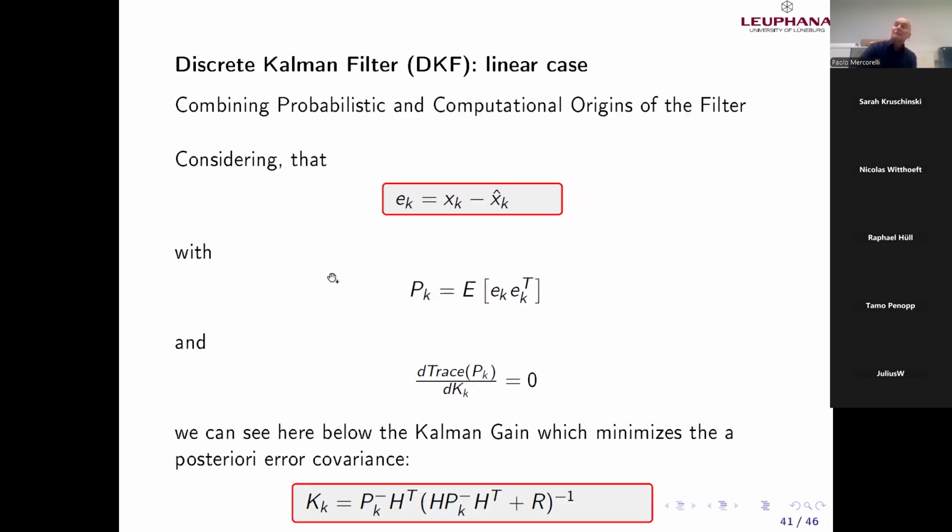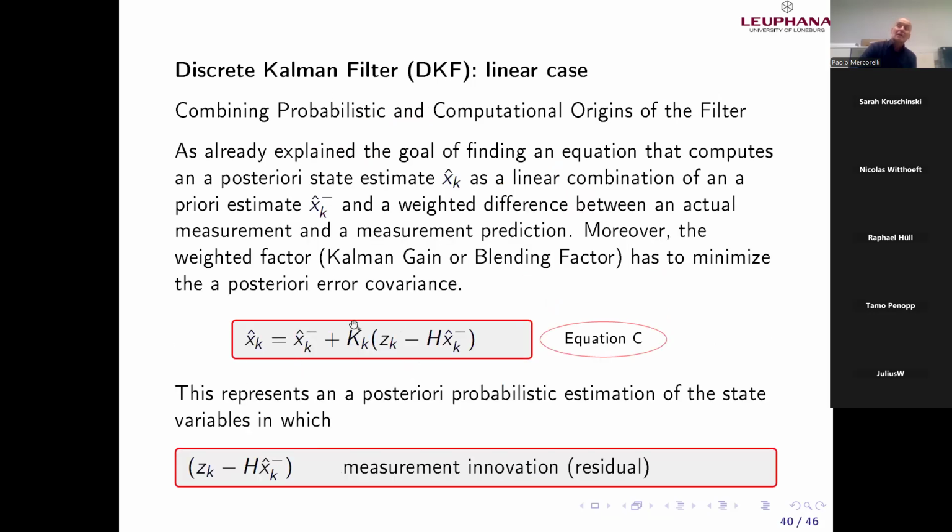We can see from this equation that I weight the innovation more strongly because I trust the measurement if R is small. Vice versa, if R is large, K will be small because I don't trust the innovation. I trust more my a priori knowledge, because if R is large, this means that the sensor or the knowledge in the equation and the output are not precise. The same consideration can be made for Q.